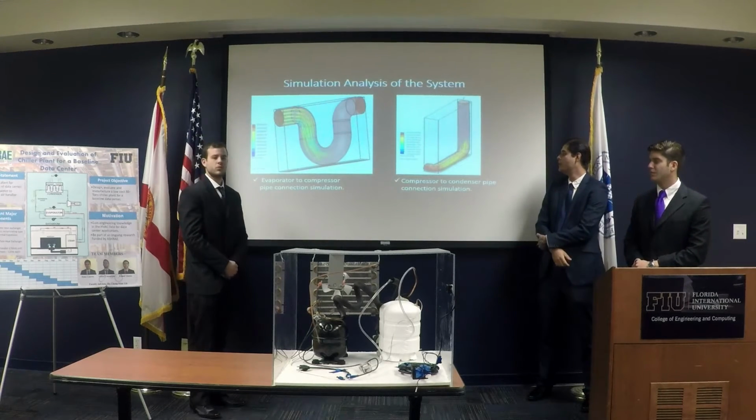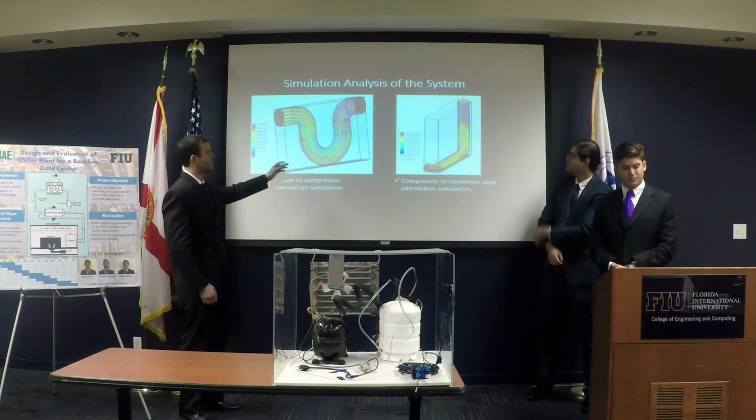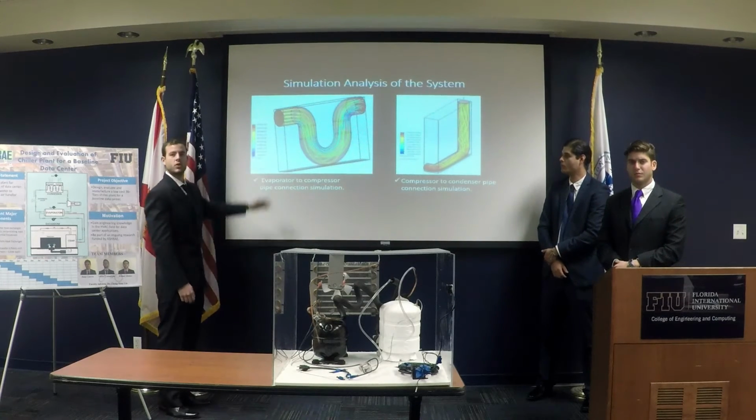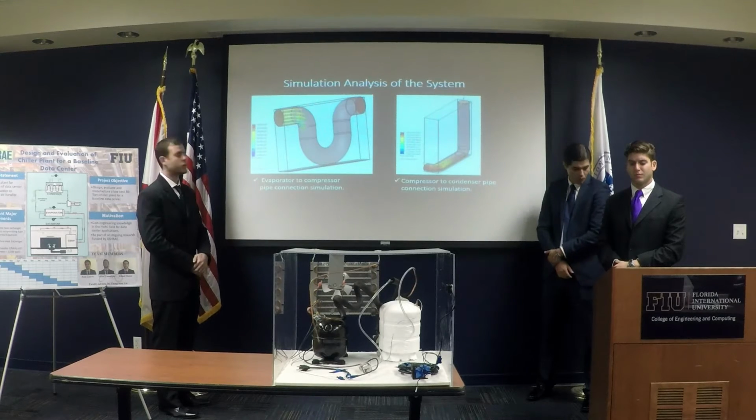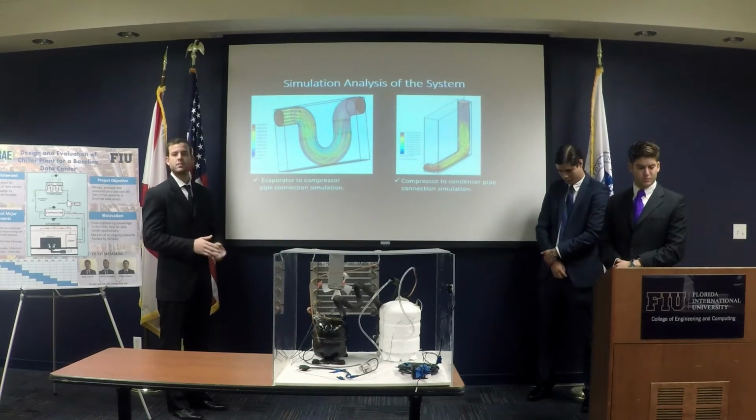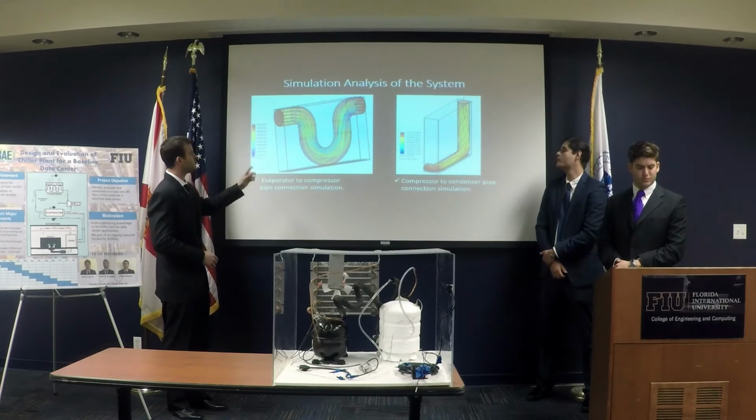This is an internal flow simulation for the suction line and discharge line. This is the pressure scale, where red means high pressure. And we did this simulation by defining boundary conditions that were static pressure and inlet mass flow rate.